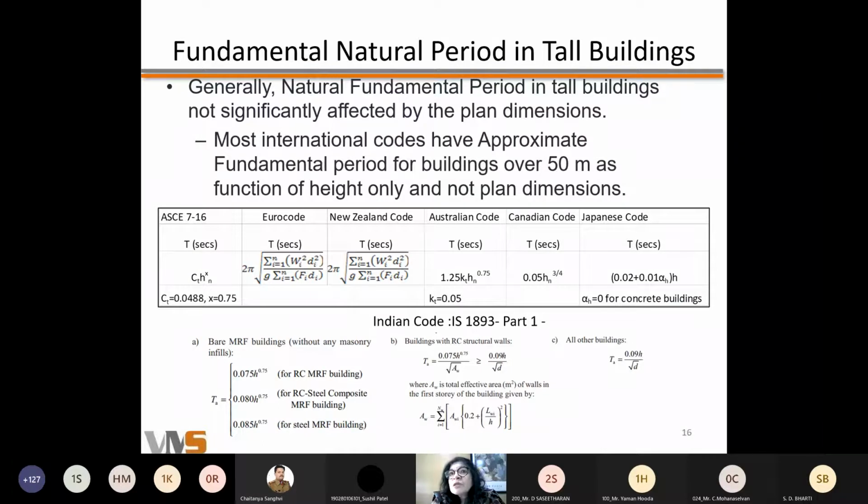So you see, in not so tall buildings, first of all, it's very often that the shorter buildings experience more of a deformation, which I would say is a shear deformation. Primarily it is a shear deformation. In taller buildings, what happens is it is more of a flexural deformation and a combination of shear and flexural deformation. But there is a difference in the way a tall building and a shorter building will behave in terms of deforming in lateral loads.